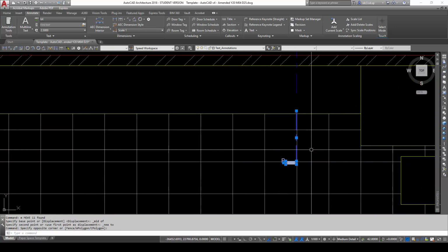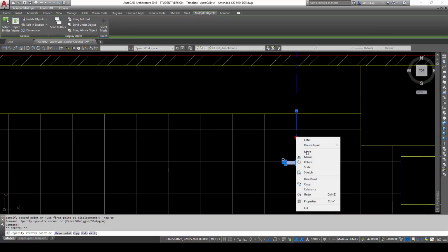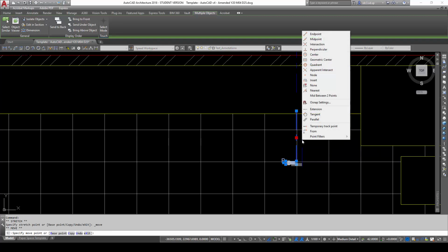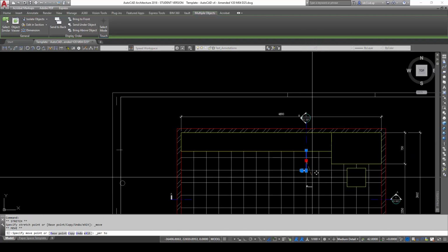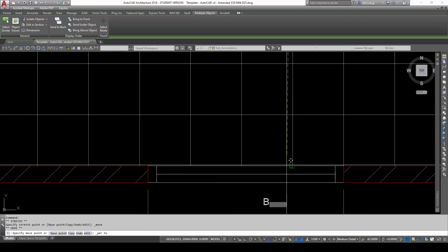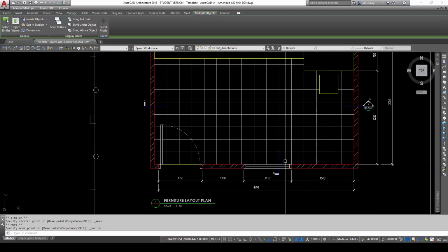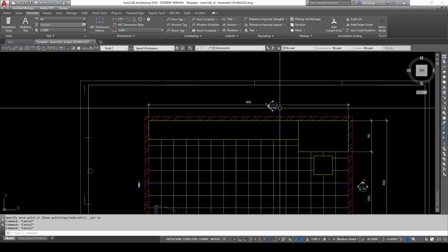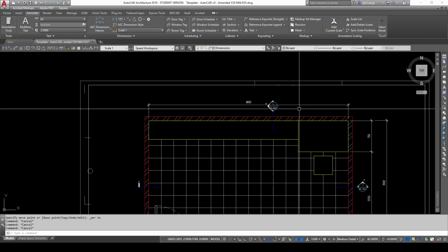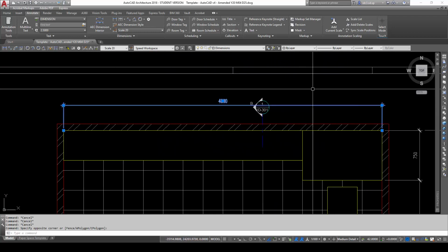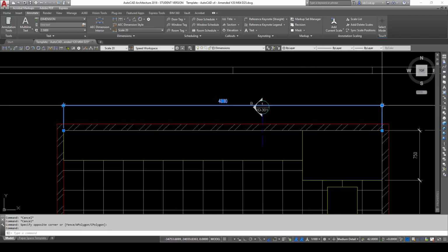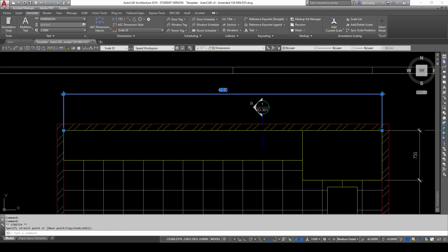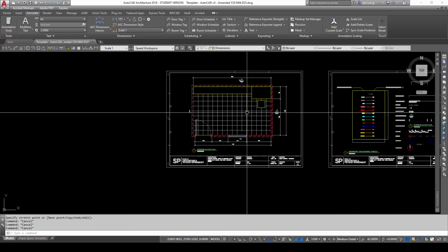And then I will move the section marker, snap to perpendicular down to here as well. Okay, and notice again I have another crisscrossing situation, so I can simply just click on this and move the dimension marker out of the way, this way here.